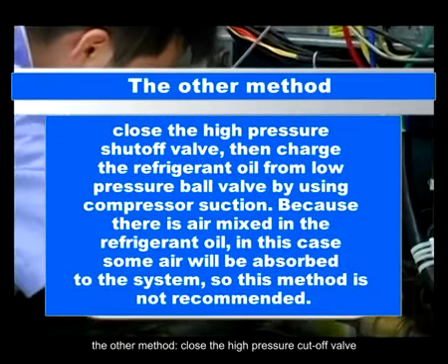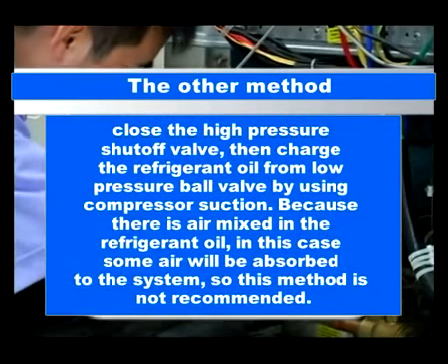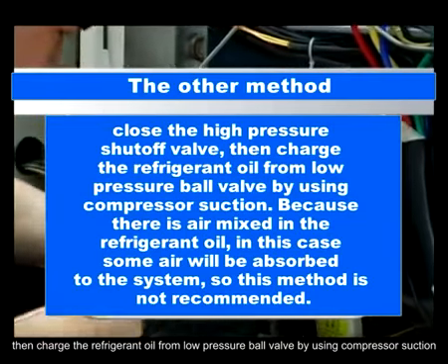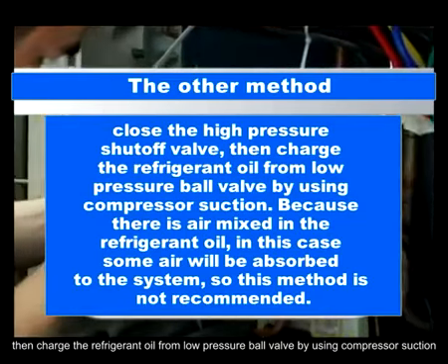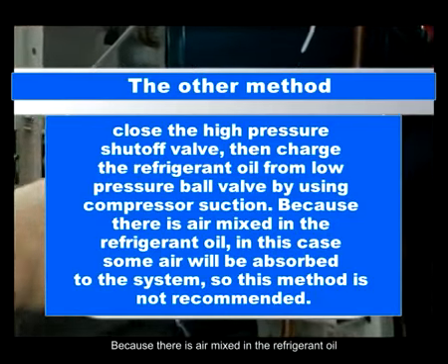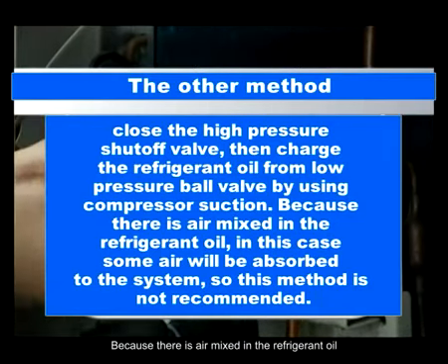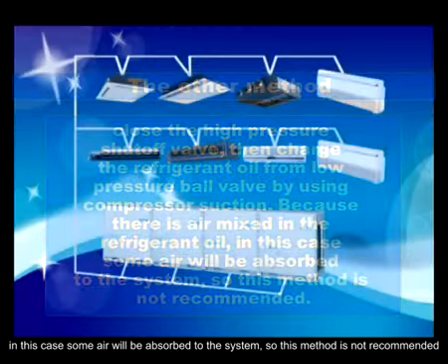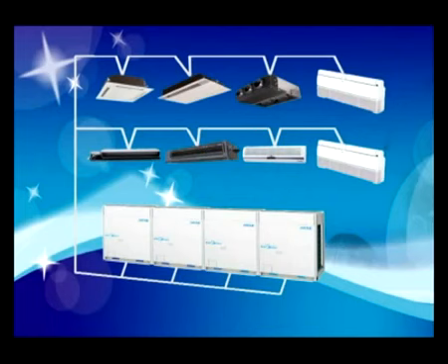The other method: close the high-pressure cutoff valve. Then charge the refrigerant oil from the low-pressure ball valve by using compressor suction. Because there is air mixed in the refrigerant oil, in this case some air will be absorbed into the system, so this method is not recommended.